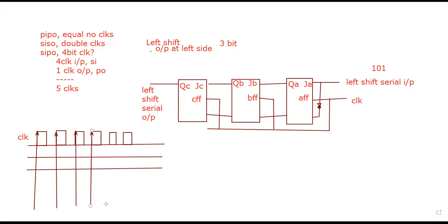So whenever we have a clock pulse, we will react on the input. We will check what the input is and what the output should be if we have a clock provided to us. Otherwise, we won't care about whatever input is provided. There isn't any meaning of input if there isn't any clock.